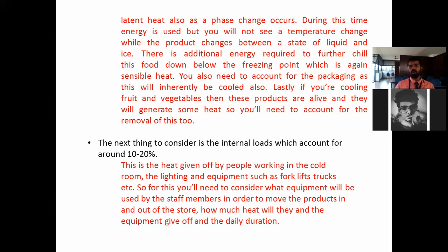You also need to account for the packaging, as this will inherently be cooled also. So you will consider the packaging also. Lastly, if you are cooling fruits and vegetables, then these products are alive, and they will generate some heat. So you will need to account for the removal of this, and you have to consider the packing of it.